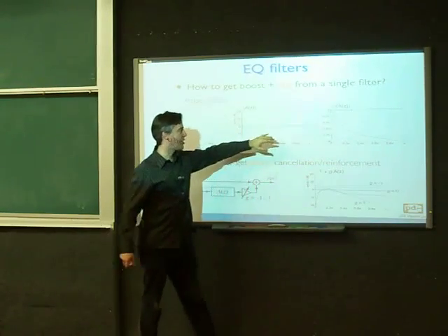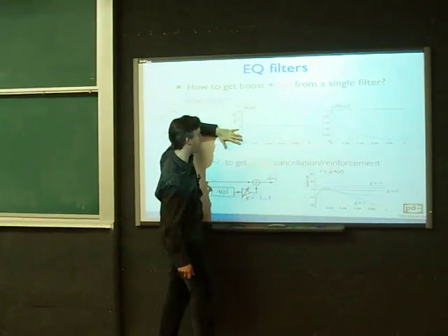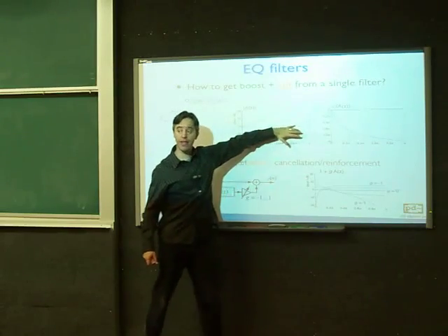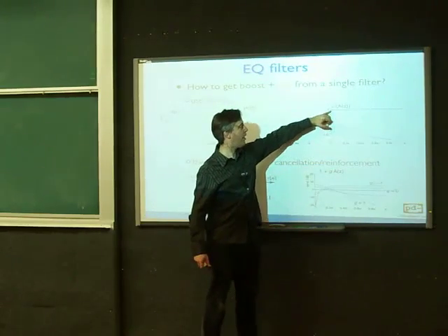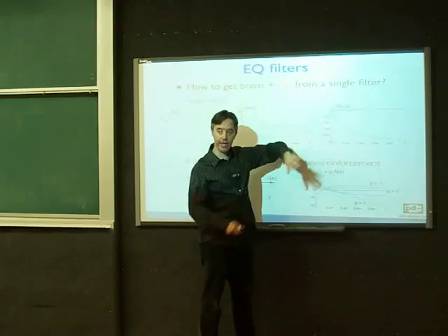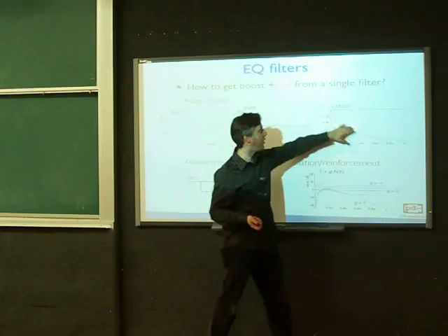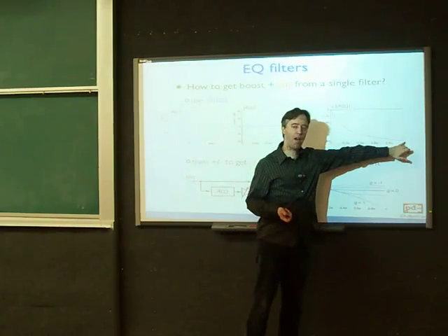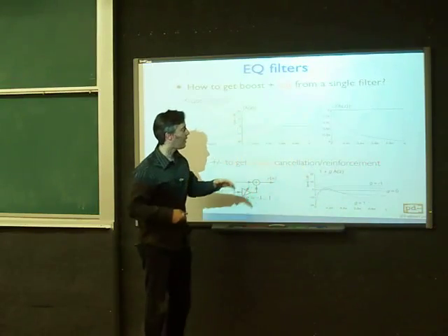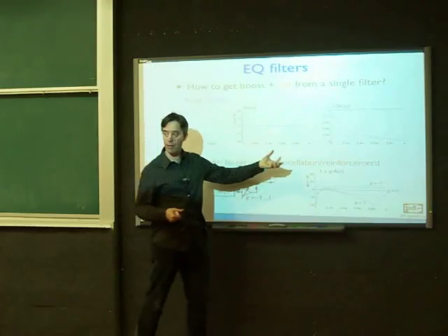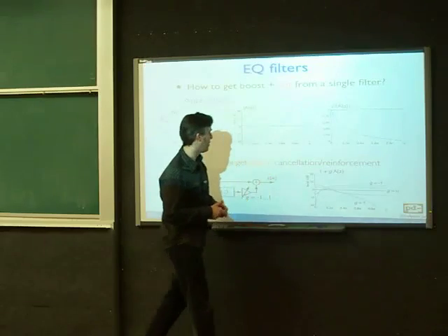And so if you take a filter but only at certain frequencies, you take a signal like this, if you add it to the original signal, its gain is 1, right? At any given frequency, the amplitude of that frequency is the same, but the phase is not the same. Where the phase is 0, if you add it to the original signal, then it'll reinforce and you'll get twice as much amplitude. But over here, where the phase is pi, 180 degrees out of phase, when you add it, it cancels out. But if you subtract it, it goes the other way around. So if you subtract it, then this is the part that cancels out, and now this one reinforces.